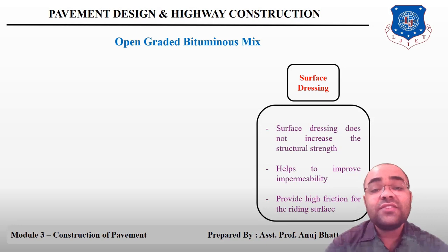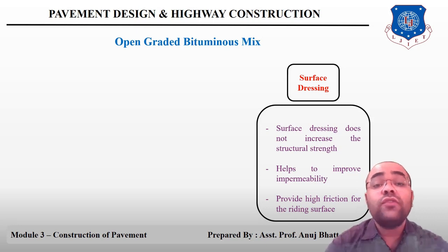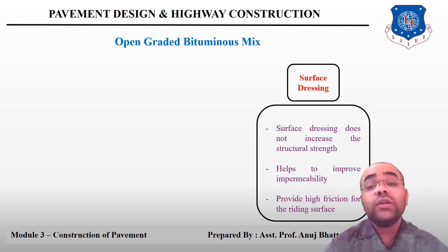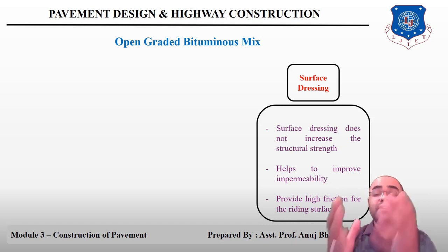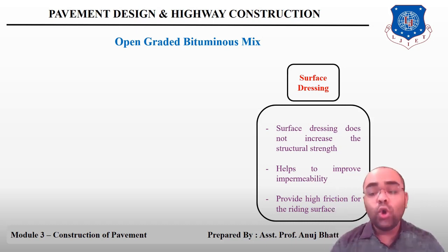Also, it provides high friction for the riding surface. This also provides a renewal coat for the periodic maintenance of the bituminous wearing surface. So these are all the reasons why surface dressing can be applied over the bituminous surface or wearing surface.